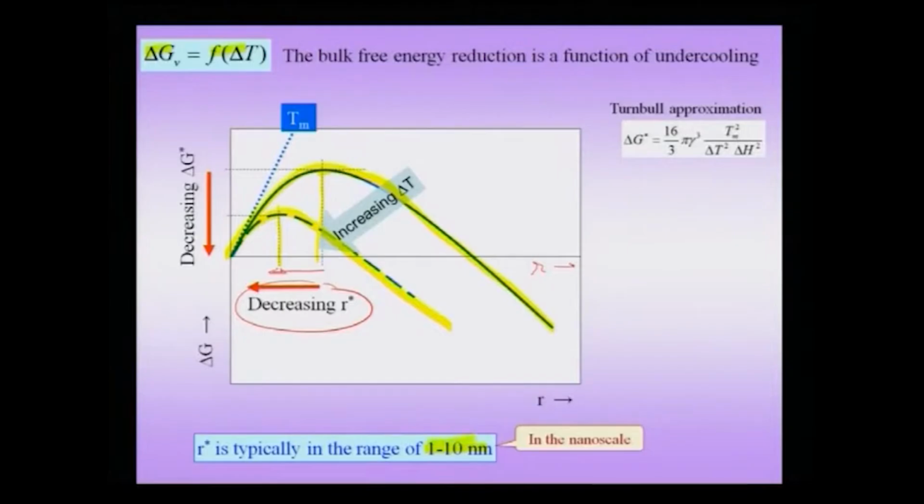Okay. So, to summarize this whole process, we are talking about first order transformations which involve nucleation and growth, and we are also talking about the fact that the melting point is only in heating; in cooling, we actually need to undercool the system. The reason we need to undercool the system is because the interface energy plays an important role and is going to oppose your phase transformation, in addition to what you might call the strain energy which is involved in solid to solid phase transformations.